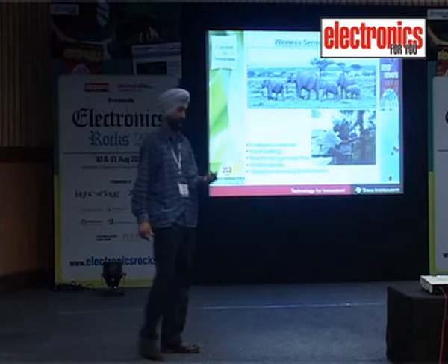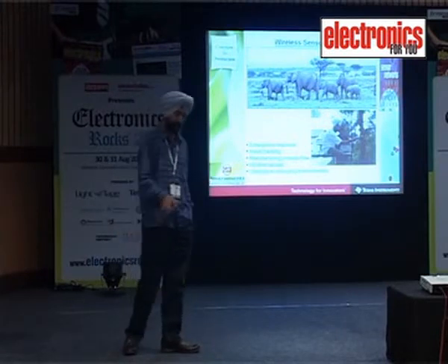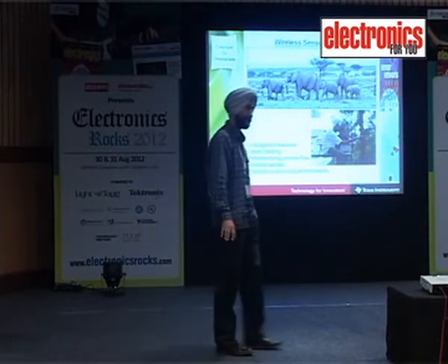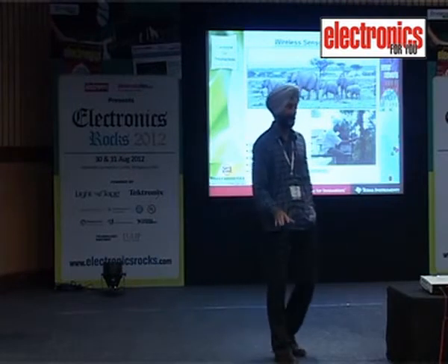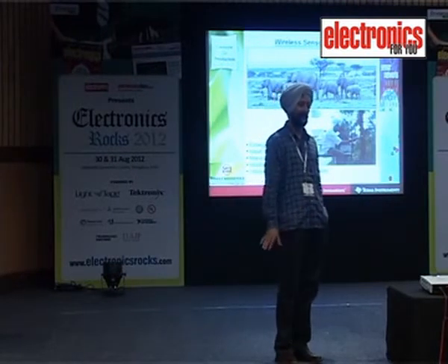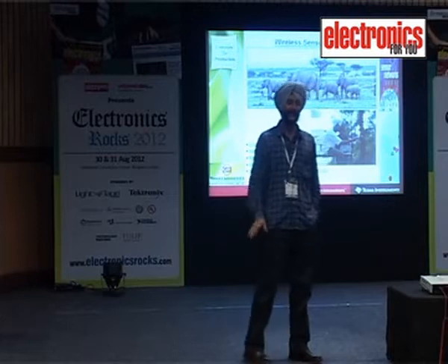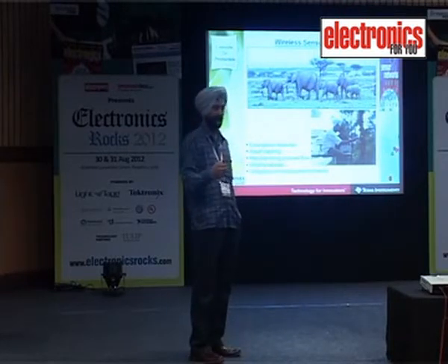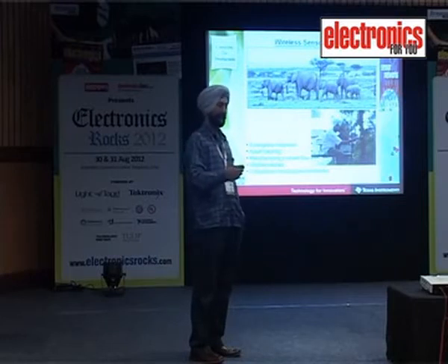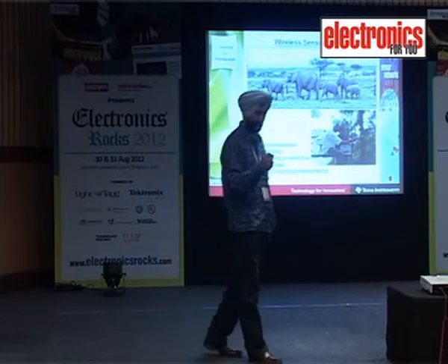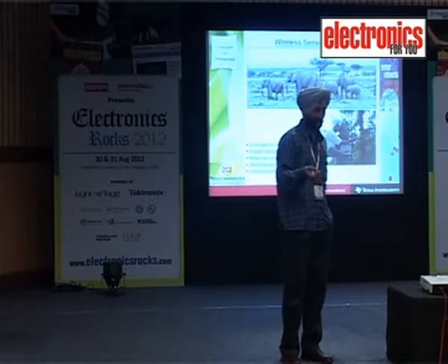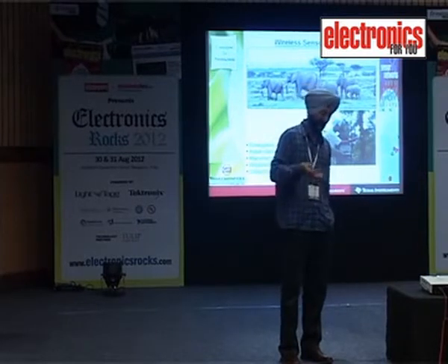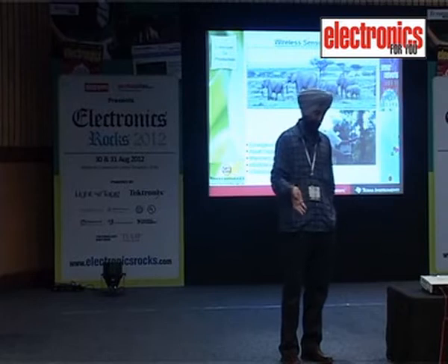So the biggest challenge is the power source, and MSP430, as we know, is the world's number one in ultra low power consumption. So it is the ideal fit for wireless sensor networks, with a built-in RF connectivity block on the same chip. Plus we have a very powerful front end, so you can have a temperature sensor, a light sensor, a vibration sensor.